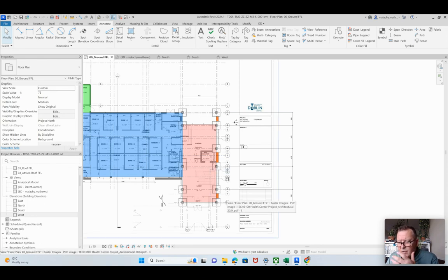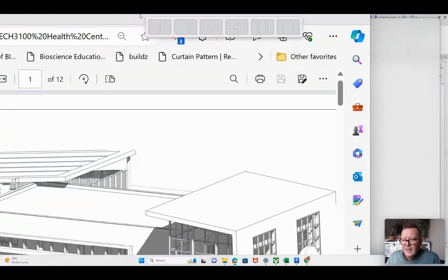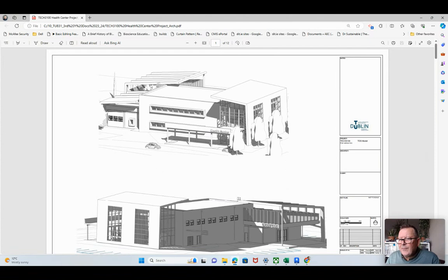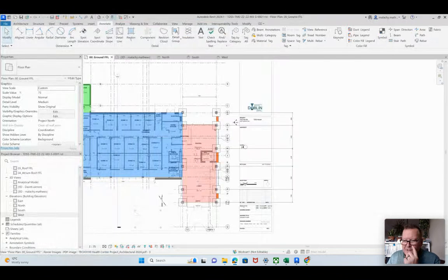We will have to bring it out in order to probably accommodate a gutter or something like that. We're not going to get that clean line. We were never going to get that clean line because you can see it's sloping down here. So we're going to have to incorporate a secret gutter in here, which means probably either oversailing the wall here, or bringing the wall up in kind of a parapet style just to the front here. So that's a kind of design decision that you guys will need to make, what way you want to go about it. I haven't decided what way I'm going to go about it yet, but I'm going to go into